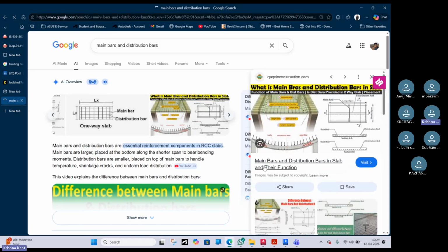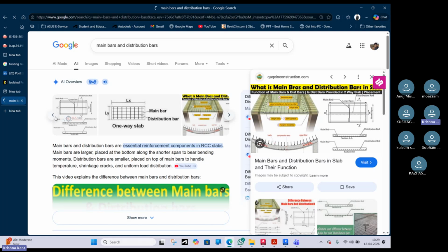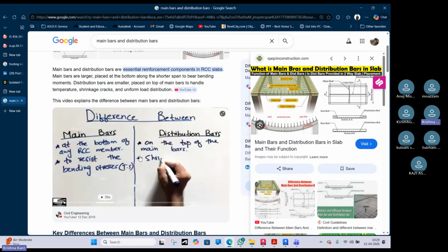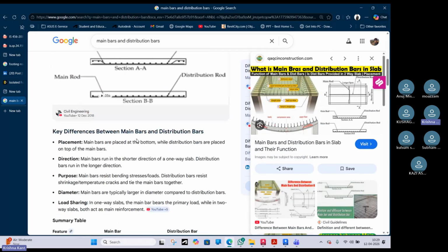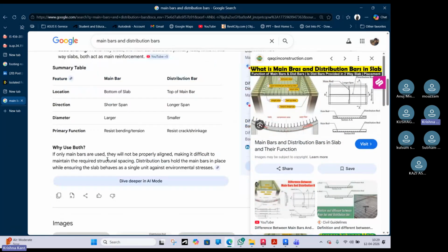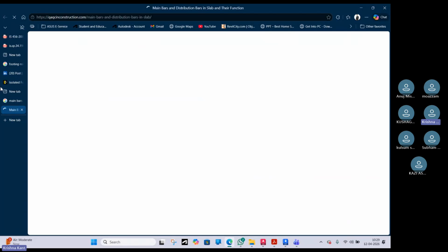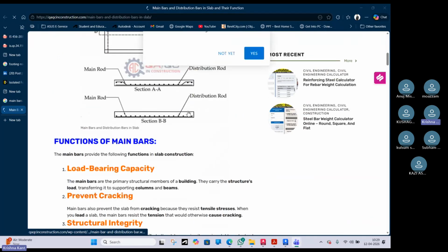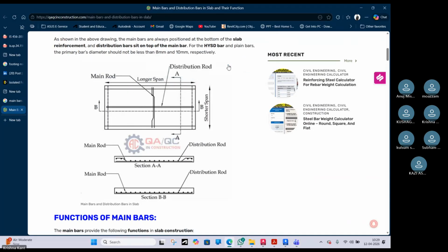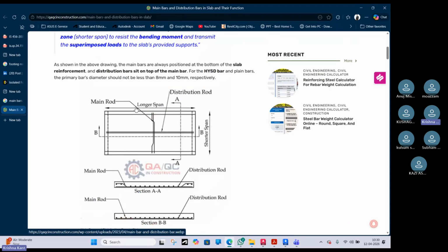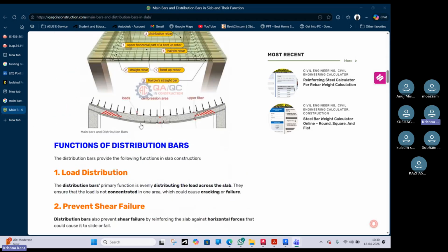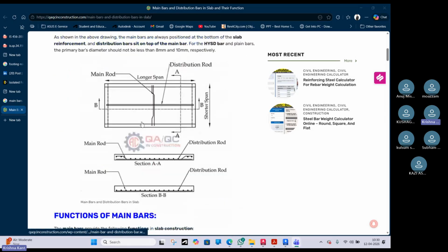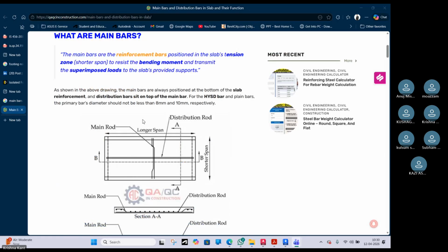First I will explain the floor. As you have already understood, when you have read these things in civil engineering, each floor is having two types of bar, one in the horizontal direction, one in the vertical direction. Okay, so both side bars can be the main bar. But the definition of when both side bars will be the main bar is basically based on the slab dimension.